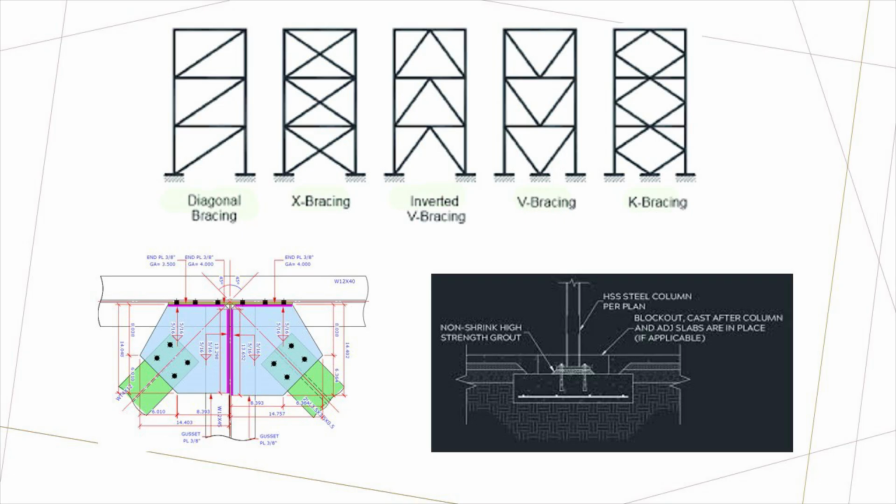Finally, the foundation system, which in this project is isolated footings, is generally sized by taking the column load and dividing by the allowable soil bearing pressure and taking the square root of that. On smaller footings or braced frames, uplift from wind can govern the design, requiring careful checks of anchorage, overturning, and soil resistance. These components collectively complete the vertical and lateral load path from the roof all the way to the ground.